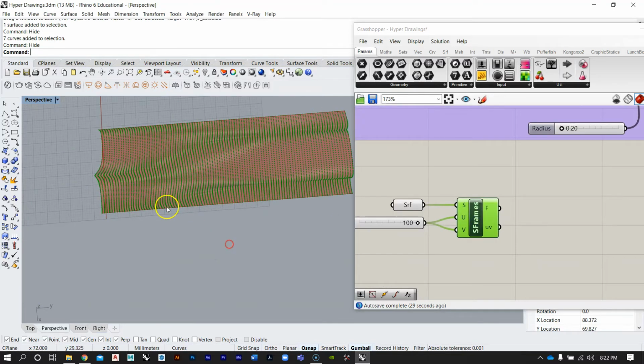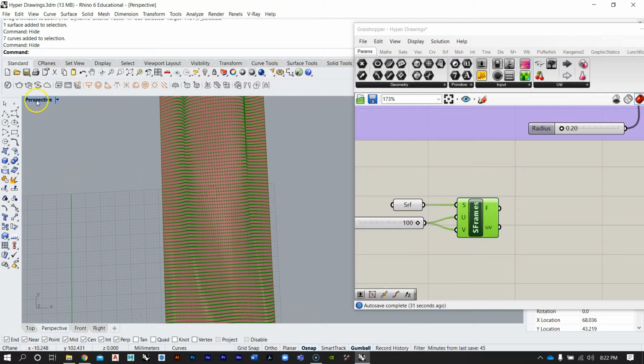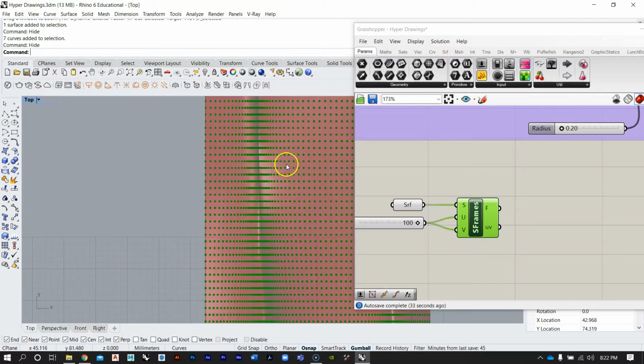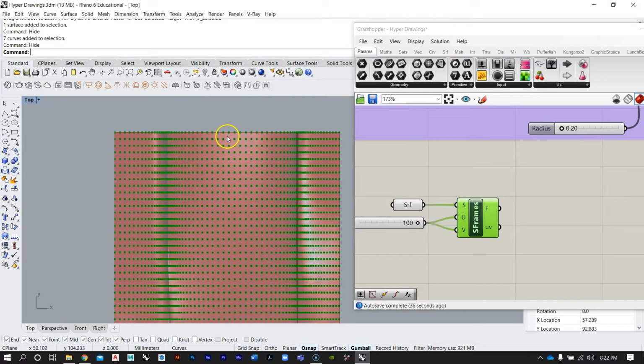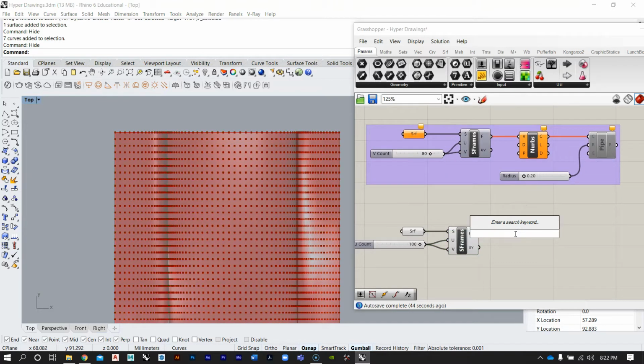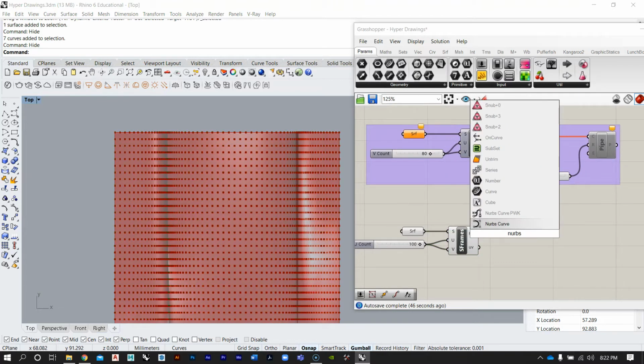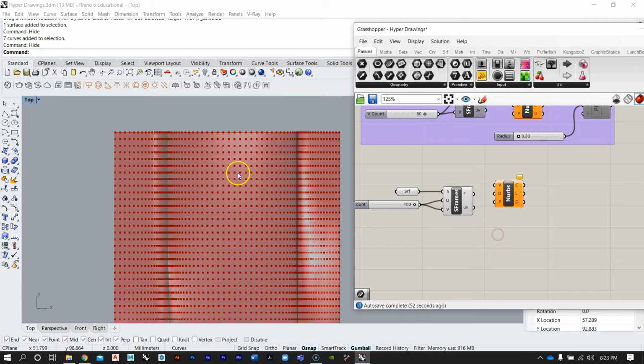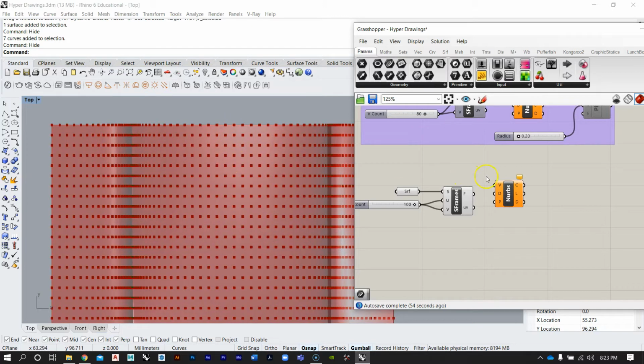And the intent is to draw a curve. So if I go into top view, it's going to be to draw a curve through each plane in one direction. And it does this pretty easily. Just double click, type curves curve. Construct the NURBS curve from control points. Our control points are going to be each one of these planes.